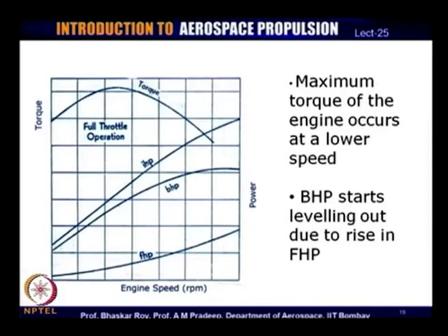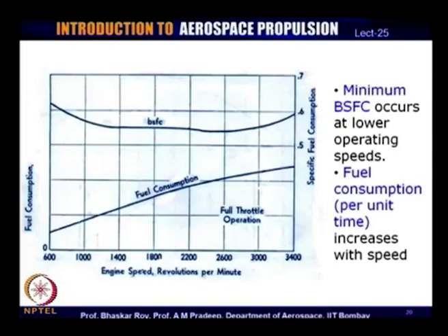And this is found out from this engine estimation before the engine is actually installed. If we look at BSFC, we have seen it is one of the most important parameters of the engine operation. It is indicative of the efficiency of the engine. However, in this graph, we see that BSFC and the total fuel consumption are two slightly different issues.